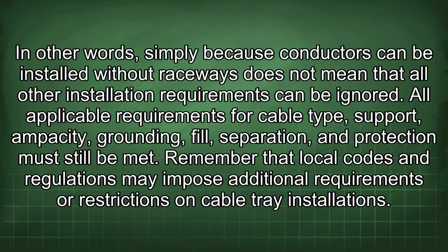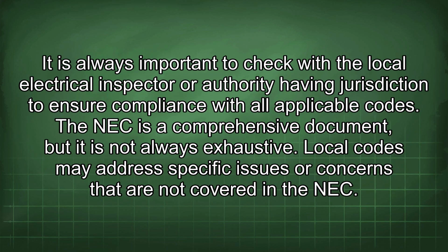Remember that local codes and regulations may impose additional requirements or restrictions on cable tray installations. It is always important to check with the local electrical inspector or authority having jurisdiction to ensure compliance with all applicable codes. The NEC is a comprehensive document, but it is not always exhaustive. Local codes may address specific issues or concerns that are not covered in the NEC.